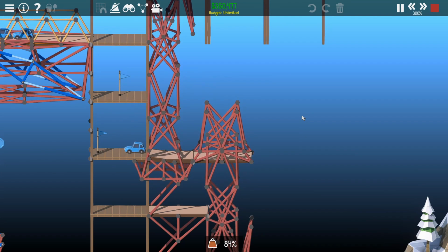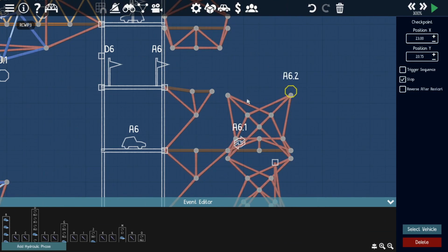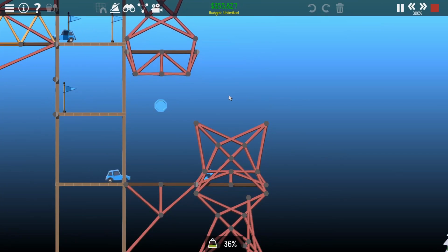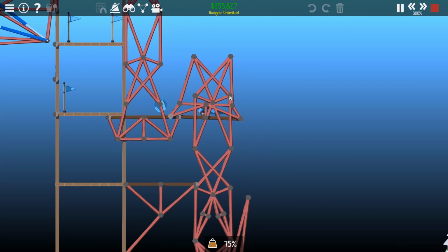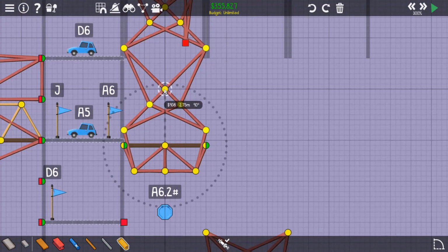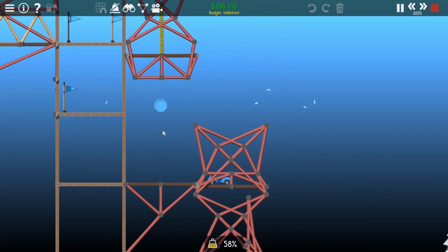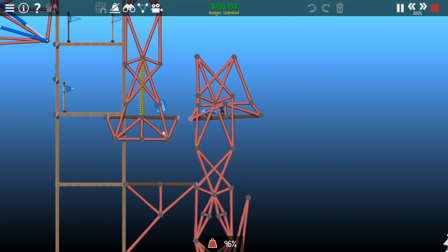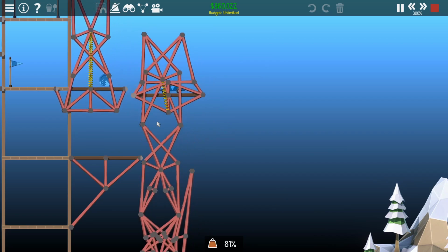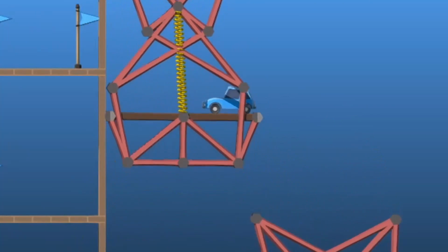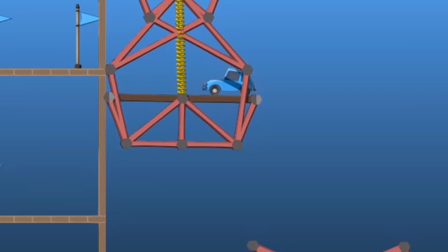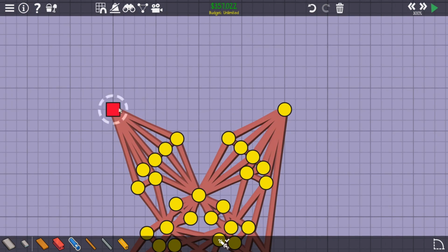But I do want the car to stop on the second scissor mechanism and then to get lifted up by it. But this is where the start of my problems occurred, because these mechanisms are swinging back and forth, as you can see. And this is because of the way they have to get supported by moving joints. I have to use swings, and I don't like it, but using some springs ends up helping the stability just a little bit. And I have a very odd problem here, where the second scissor mechanism doesn't pull up all the way to the full distance it originally came from.